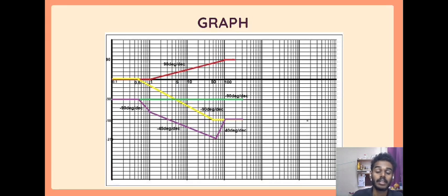So this is the graph, and the graphical results show us the phase progression starting at negative 90 degrees from the pole at origin. It makes a steep transition around omega equals 5 due to the double pole, reaching about negative 153 degrees at omega equals 5, and then negative 180 at omega equals 10.